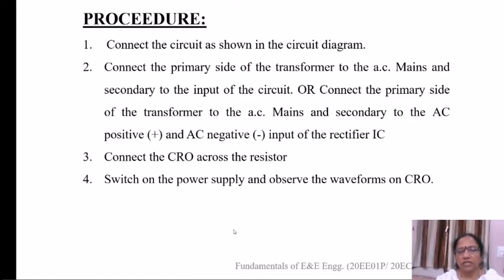After the connections, switch on the power supply and observe the waveforms on the CRO. So the CRO is connected across the output load resistor. This output load resistor is the same for the 4 diodes connected in bridge shape as well as the rectifier IC.